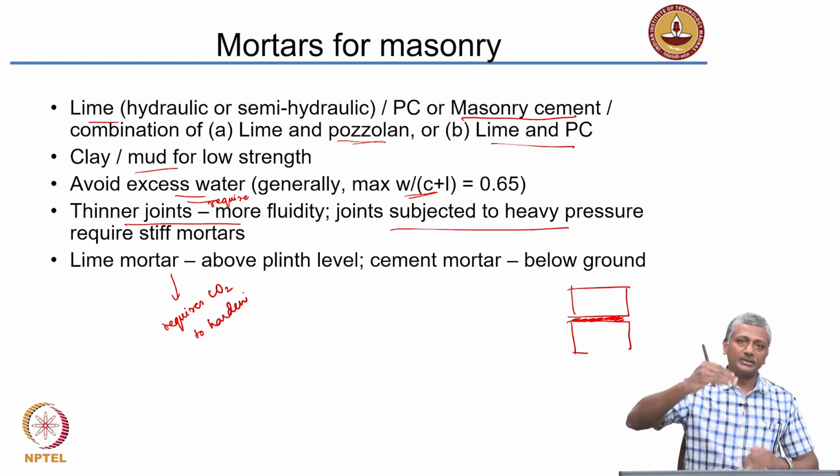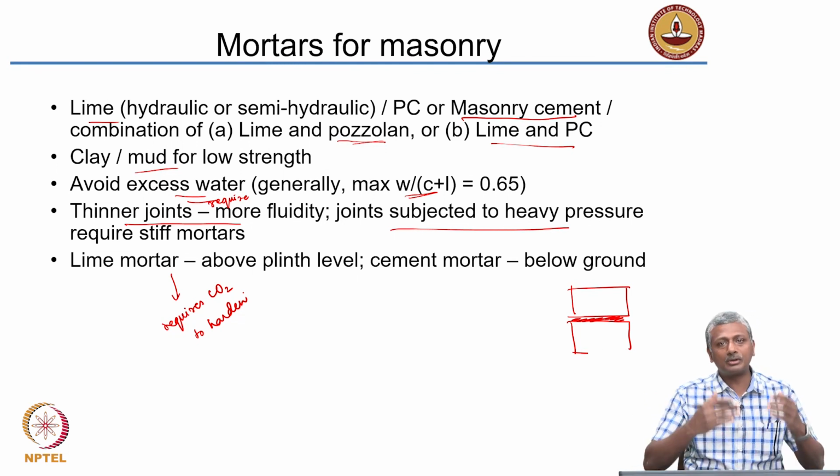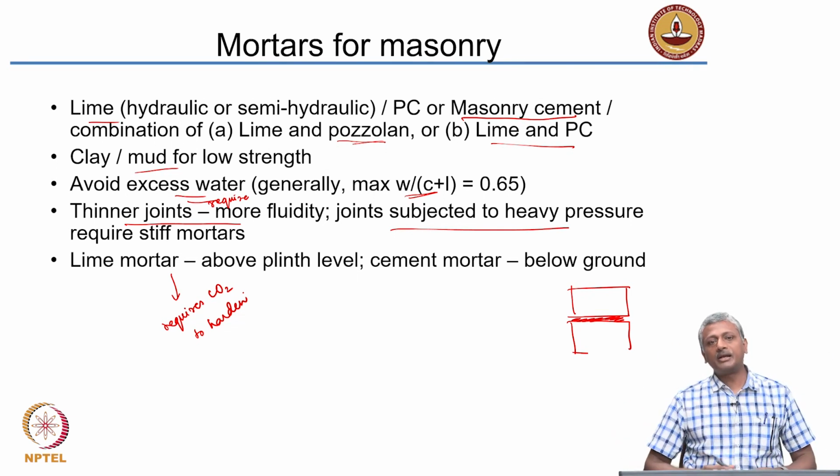So, in the superstructure, you can use lime mortar, but today of course, people use cement mortar all through. If they are going to be doing block construction for the foundation as well as for the building, they typically tend to do it just with cement mortar.